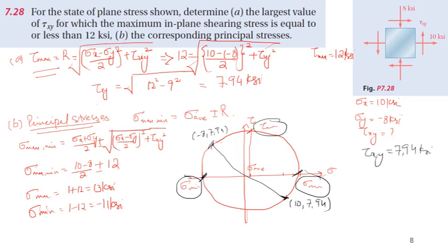We don't use the Mohr circle that much these days because we have a lot of computational power, but if you want to find the principal plane, we can find this angle, and in the Mohr circle it will be 2 theta p. And this angle will be 2 theta s. Okay. Now you can solve the problem as given in the assignment, and it will make clear the concepts related to the principal stresses and shear stresses.